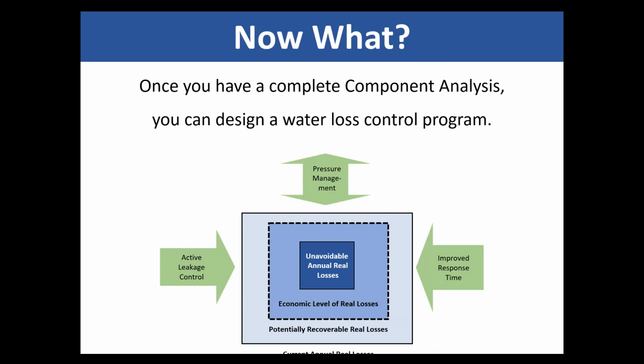And also on the flow rates, since you're assigning flow rates to each event, right? You have a 4-inch main break, for example. Some of you make an estimation on site, some don't. If you don't do that, then you can use the model and use some industry flow rates, where simply it's multiplying duration by flow rate that calculates the volume. So that's not an issue if you don't do that.